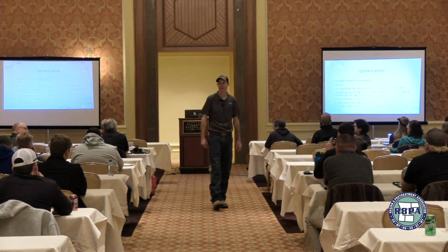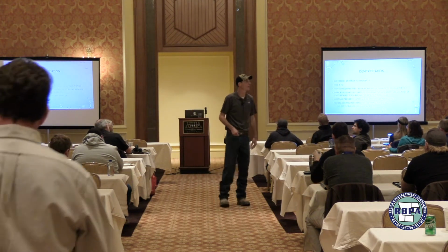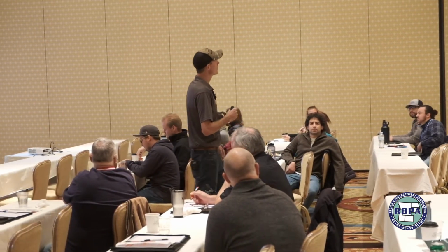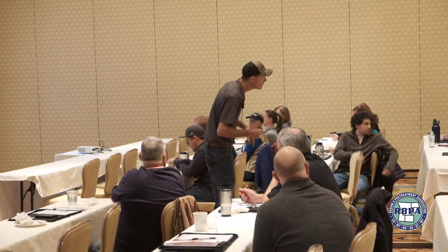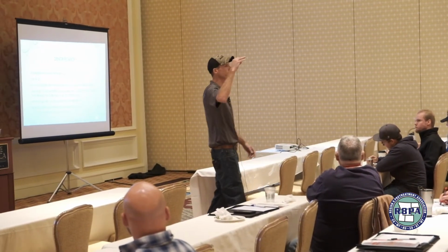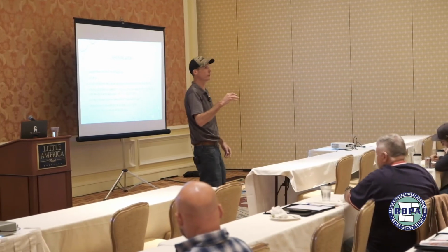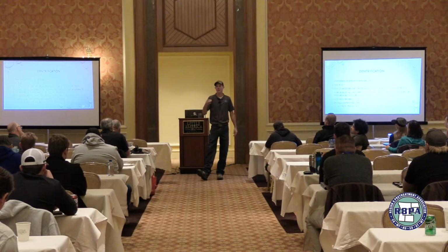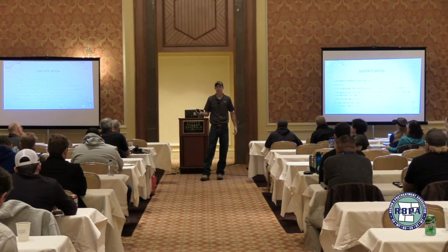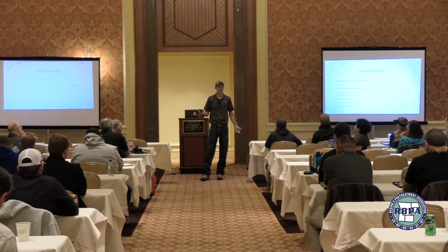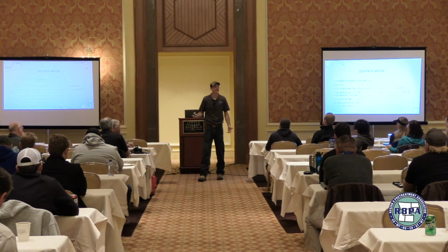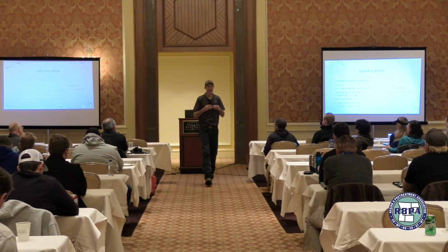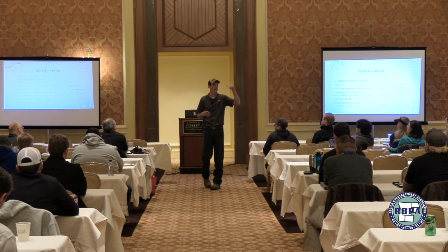That's an aerobic condition. Now, denitrify, where's that level? Positive 50 to negative 50 is primary, and lower. Positive 50 millivolts to negative 50 millivolts. Why are we talking about electricity when we're talking about poop? Right? Nobody cares. It's a much more accurate scale to measure your nitrification and denitrification.